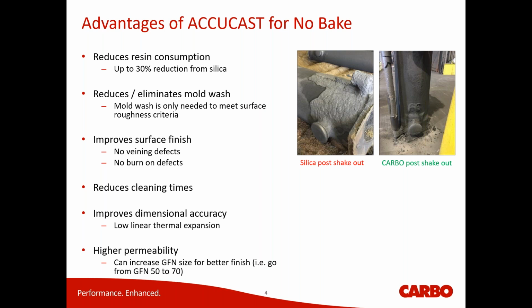We're now going to move into no-bake. With no-bake, we see a lot of great advantages with going with a ceramic media. The first one is the resin reduction. We've seen up to a 30% reduction in resin from silica. So that's a very nice cost savings to start out with.